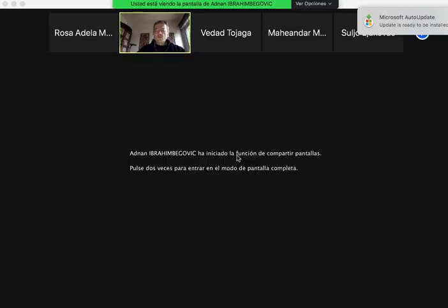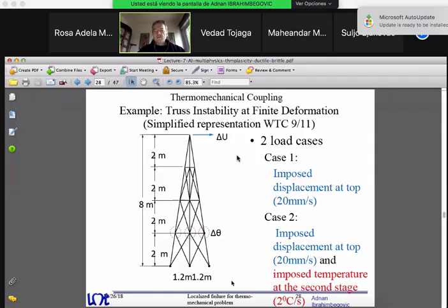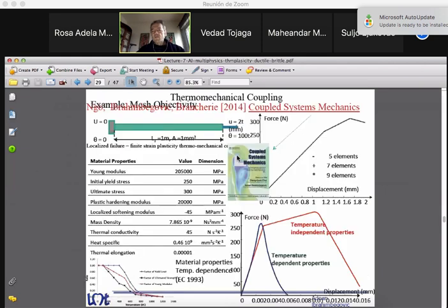So going back to this work, what we have done after that is carry out this simulation. First of all, when you have a thermomechanical coupling, of course, you need more of these data. So we chose something that is typical of steel. That's E equals 2 times 10 to the power 5. Yield stress is 250, so it may be a little bit smaller quality of steel, with the ultimate stress being 300, then plastic hardening modulus is roughly 10% of this. And then softening moduli and so on are produced in order to be able to carry out this computation.